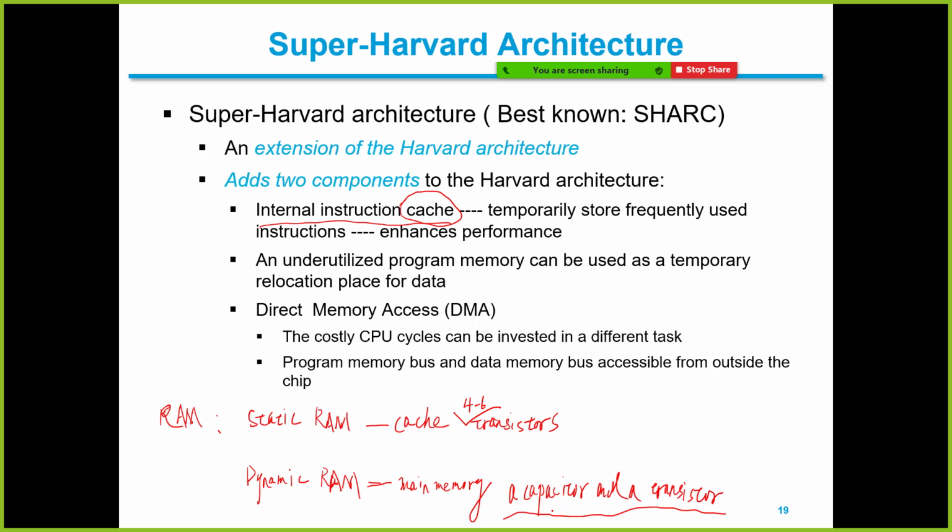So usually a couple of milliseconds. Although it's in milliseconds, it's very fast to us, but for the CPU, a millisecond counts. During that refresh operation, the refresh cycle, the memory is not accessible, so you cannot read any data during that cycle. You have to wait. So that refresh operation will lower the speed of this dynamic RAM.